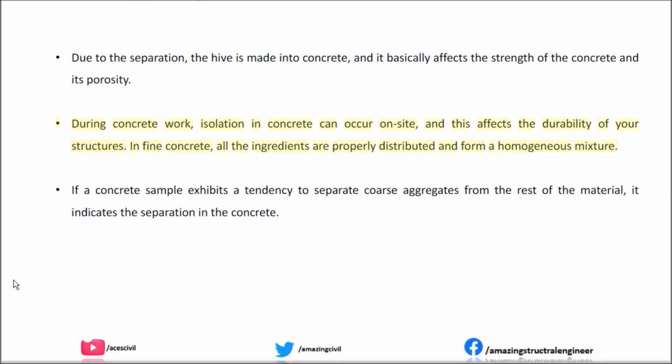During concrete work, segregation in concrete can occur on site, and this affects the durability of your structures. In good concrete, all the ingredients are properly distributed and form a homogeneous mixture. If a concrete sample exhibits a tendency to separate coarse aggregates from the rest of the material, it indicates segregation in the concrete.